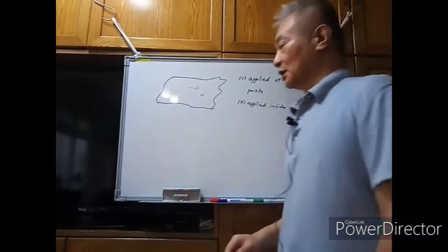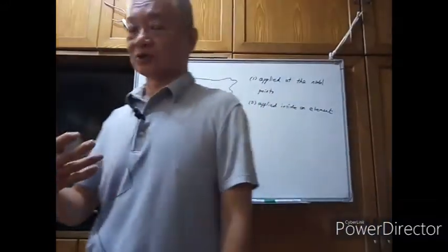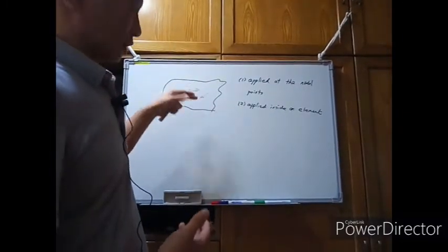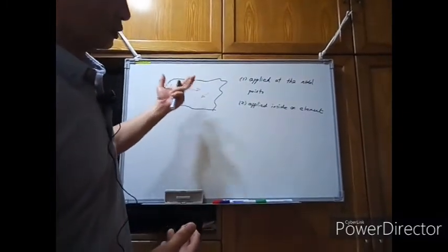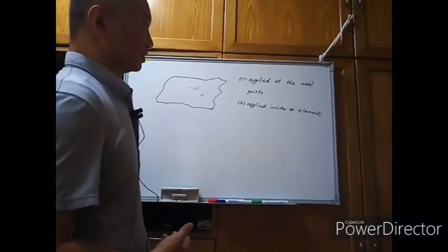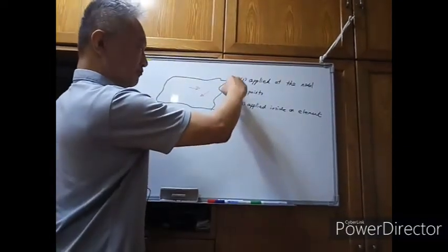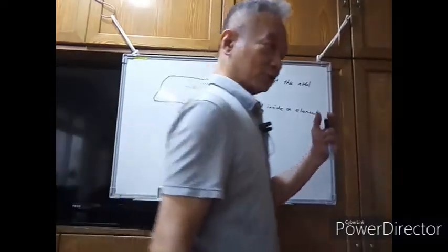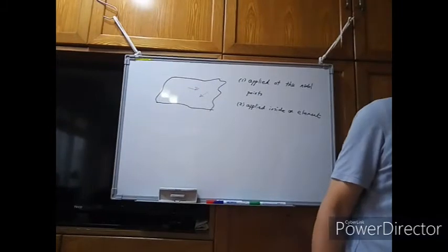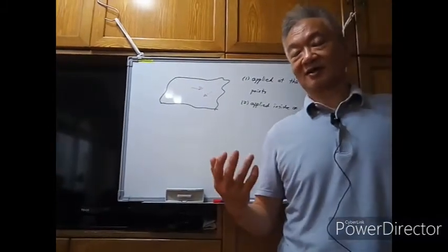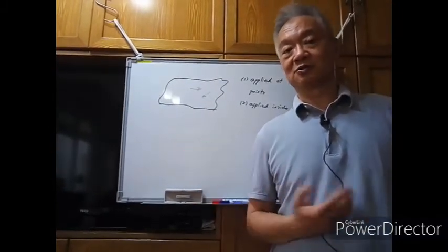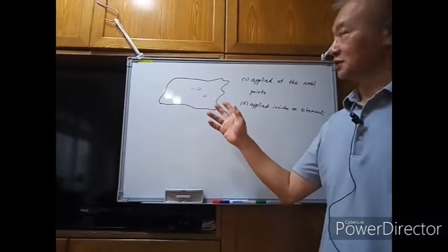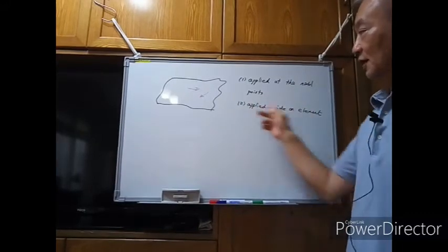But if you are doing structural analysis, you had better choose the first type, since if the concentrated loads are applied at the nodal points, then you can get better approximations. So it means the solutions will be more accurate compared to the second type of the loadings.